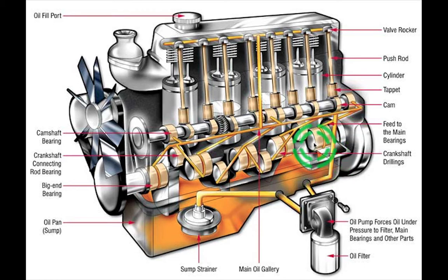They are not belt driven, because you don't want the belt to break, because like I told you, it can't run without oil. So if your belt broke, your engine fails right away. So it's connected right at your crankshaft and stuff like that. It's mechanical, so ideally it should never fail. So that's the whole thing.